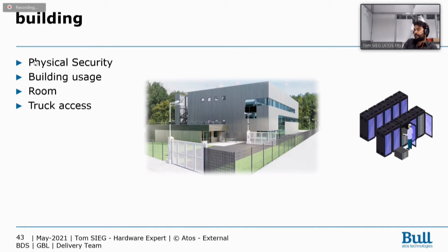Putting a data center at the highest level or the last level of the building is not a good idea either, because it's really heavy, and you will have a cooling system in all cases. So you will have to bring water into this room, and you don't want water at the top of your building, to prevent any water risk.